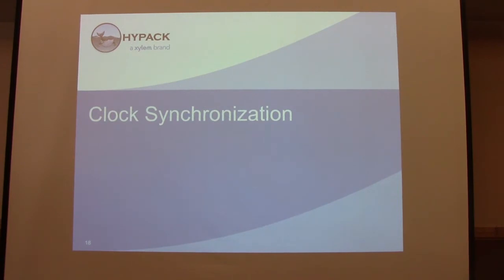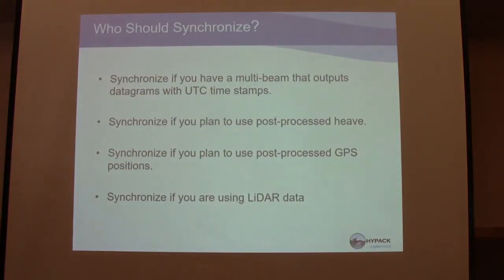Okay, so the next thing that's real important for multi-beam is clock synchronization. This is probably the most important thing for multi-beam. This is probably something that we get the most calls on as far as multi-beam goes. If people are seeing artifacts in their data or just not seeing their data at all, it's probably because there's a timing issue. There's either a software setting that hasn't been set correctly, or there's a hardware consideration that the customer didn't use.